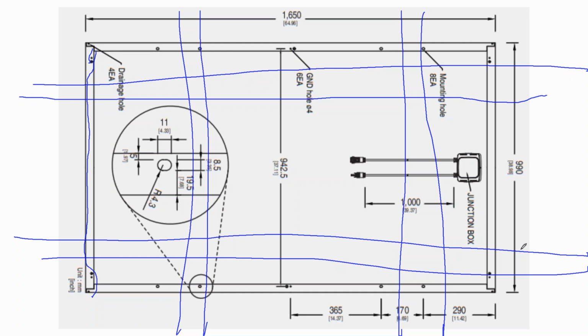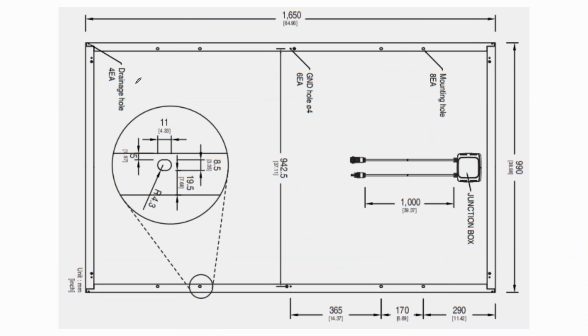And not all solar panels being made out there are flexible. Back in the day, every module was so robust, with a big, robust module frame, that you could pretty much do whatever you wanted with it. Mount it portrait, mount it landscape, whatever. Nowadays, pricing is so competitive that in some ways, modules have gotten 10 times better in terms of quality, but manufacturers are looking at, hey, if we can cut out this little strip of metal here, how much money are we going to save? And sometimes that means your module is not as flexible or as strong as it has been in the past. So you can pick up on whether it has a full frame or a weakened frame and what that might mean to your design if you get really good at evaluating a module spec sheet.